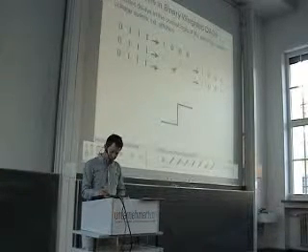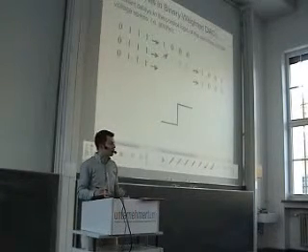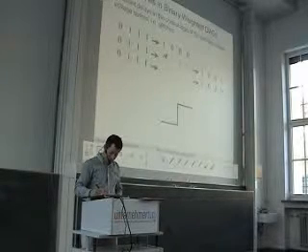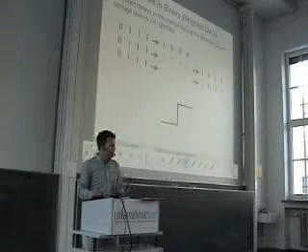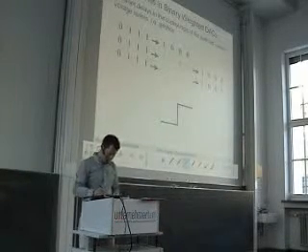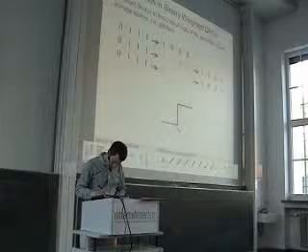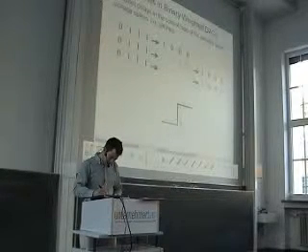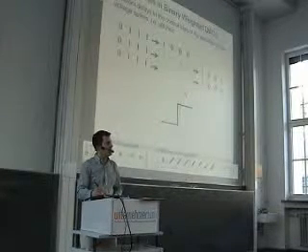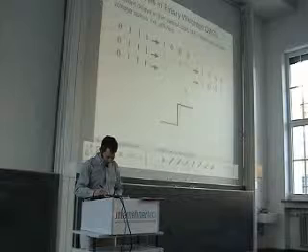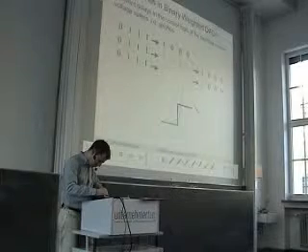However, during that intermediate time we have all bits set to 1, which means that the voltage tries to rise to much higher values, and then we toggle the other bits and it goes towards the final value. So we start from this voltage, then we put all bits equal to 1, so we shoot up, and then after a while the other bits switch, so we go down again, but at the end we have a kind of overshoot.